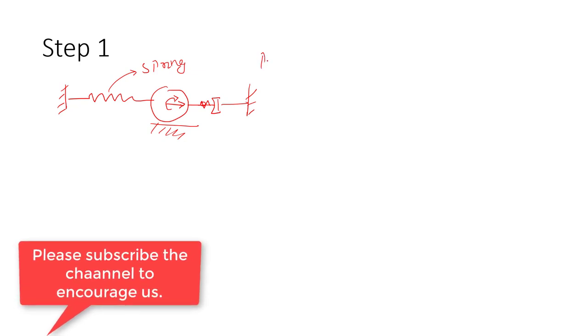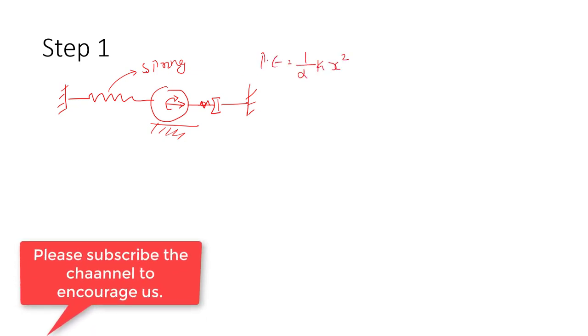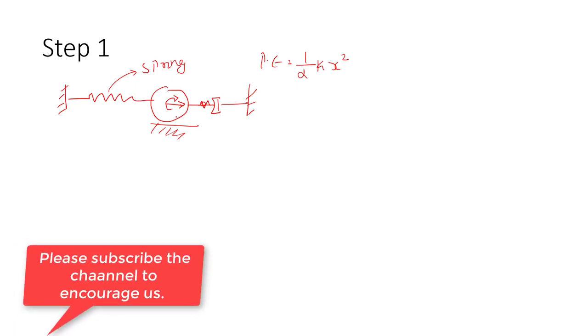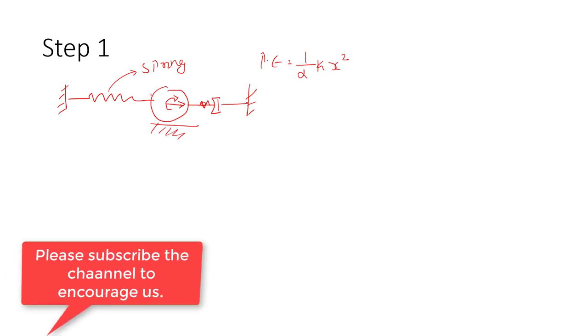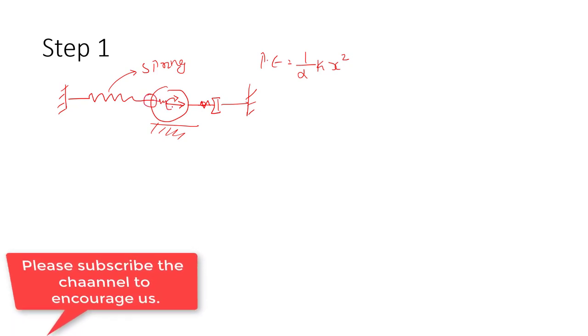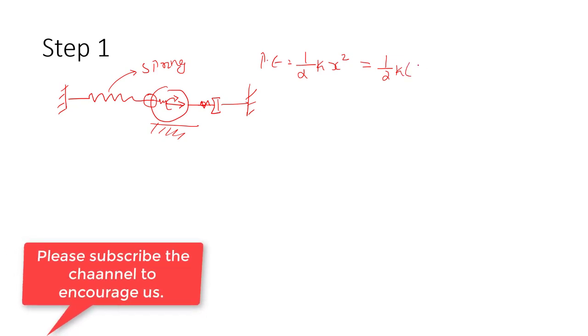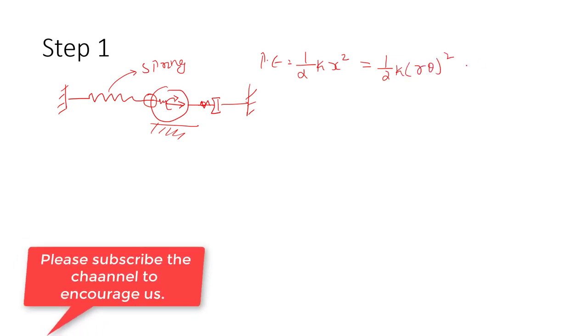Now if we recall, the potential energy for a spring is half k x square, because even though it is rotating and moving in this direction, this spring will stretch, or if it is vibrating then it will stretch and compress. So we can write half k, and x is equal to r theta, square.